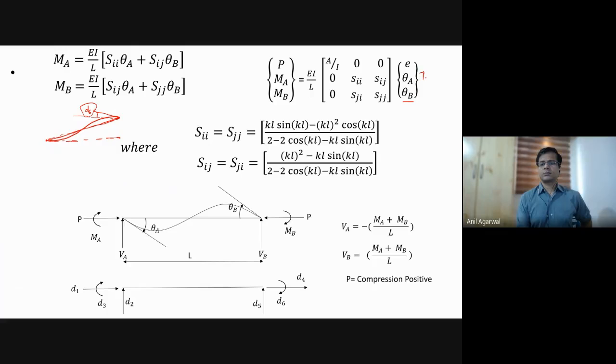The other part that is missing is on the force side. If you look at the force side, I have only one axial force value, just like in the displacement side. But actually, when we developed the stiffness matrix, we did not have one axial force. We would have one force acting in this direction, one force acting in this direction, in each degree of freedom. So even these values should be corresponding to each degree of freedom rather than just the axial force value.